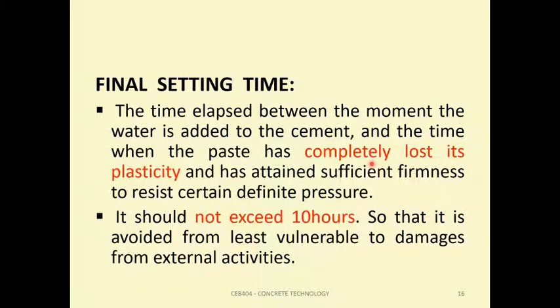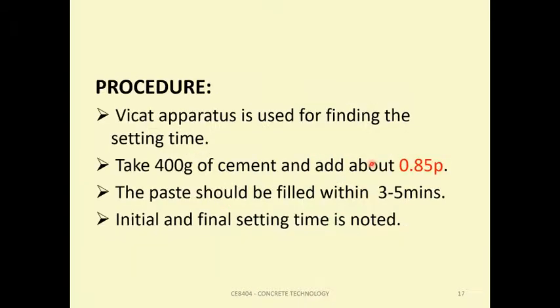The next one, final setting time. It is the time elapsed between the moment we add the water to the cement and the time when the paste completely loses its plasticity. That is, it attains sufficient hardness to resist a certain definite pressure on it. It should not exceed 10 hours so that it can avoid damage from external activities.